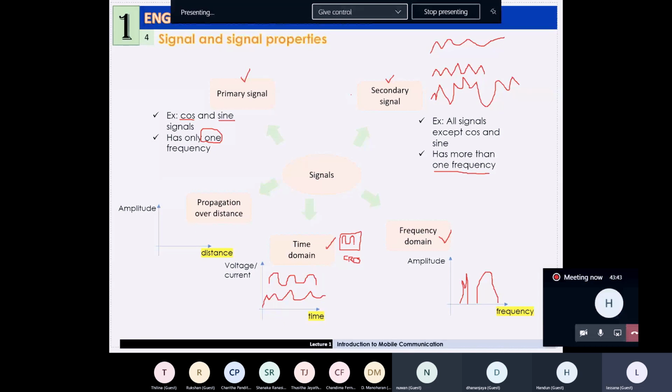And at the same time, there is another device, maybe you have not heard of it, called a spectrum analyzer, and that device can show signals against frequencies. So that particular device can show the frequency content of a particular signal. That is normally what we call the spectrum. Therefore, this particular device is called a spectrum analyzer. A spectrum analyzer is a device that tells you something about the frequency domain.